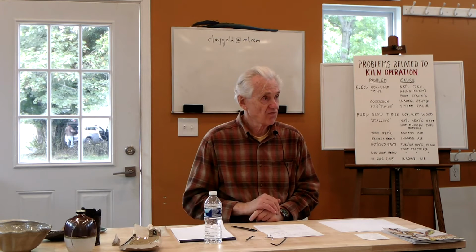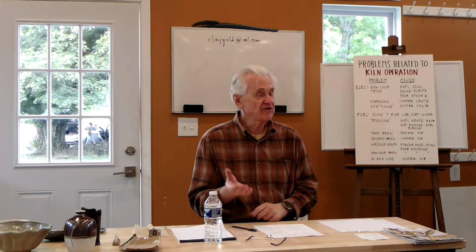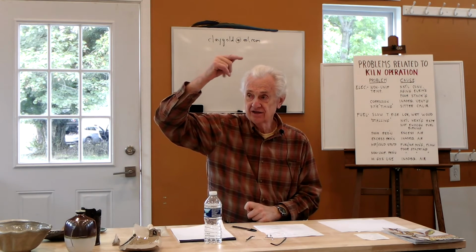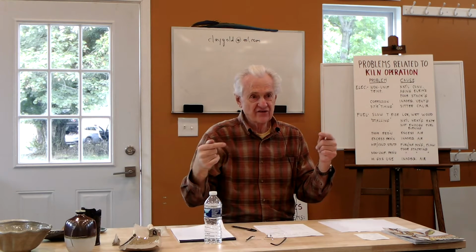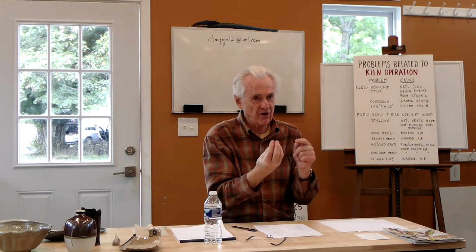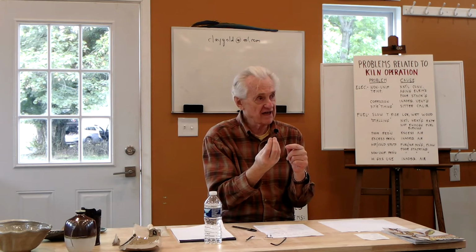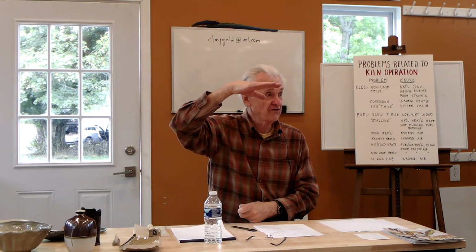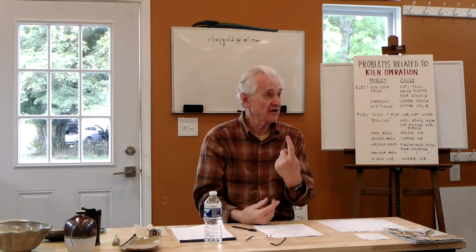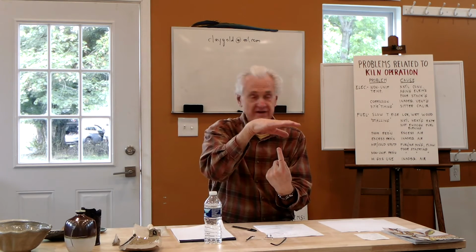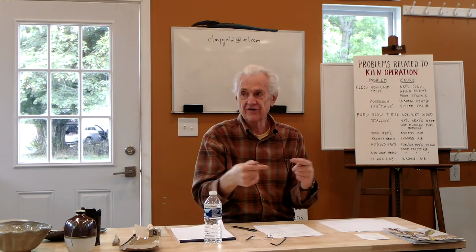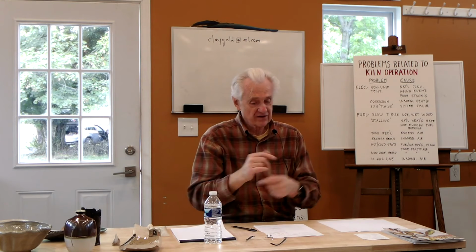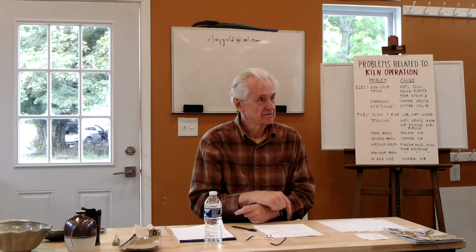Why can't the carbon itself react? There isn't enough air to react it. This is the same reason you get soot out of a candle when you hold your flame. A candle flame, you get air coming into the outside of the flame, but there's still a portion of the flame in the center that isn't getting enough air, and that's one of the sources of the soot. Even though it's out in the open air, you still get soot off a candle flame. That's why, because there isn't enough air getting into the center to burn all the carbon to convert it to carbon dioxide.